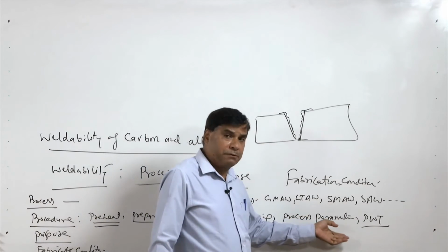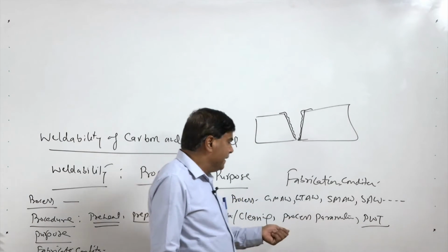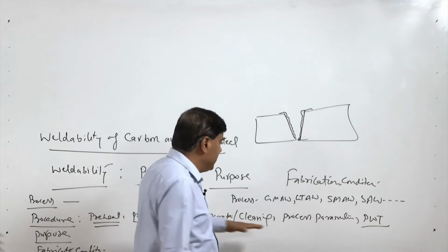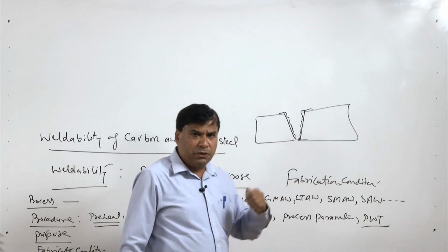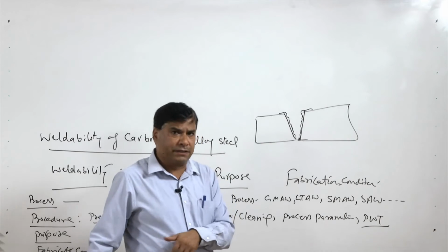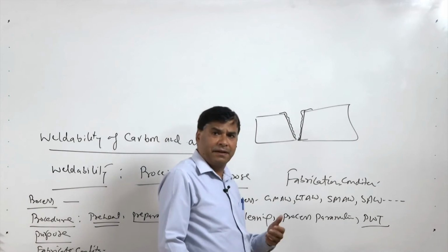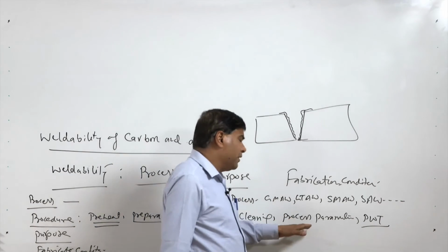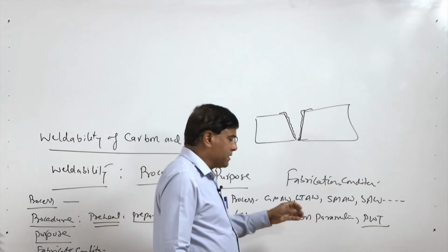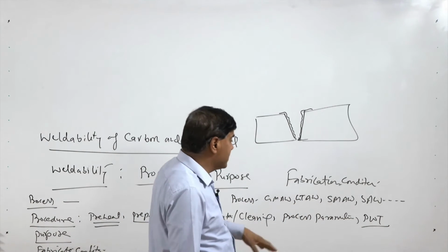Similarly, the selection of proper process parameters also affects the ease of welding. If too high heat input is used, then it will degrade the heat affected zone, it will result in undercut, it may lead to a lot of thermal damage to the workpiece, and a lot of residual stress and distortion tendencies will be associated with it.